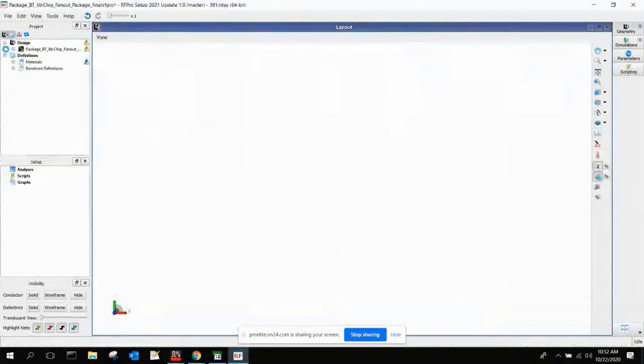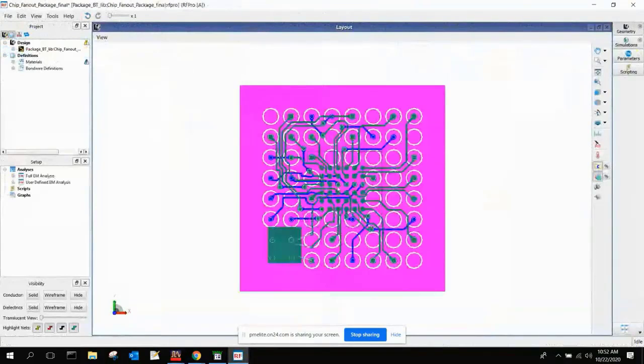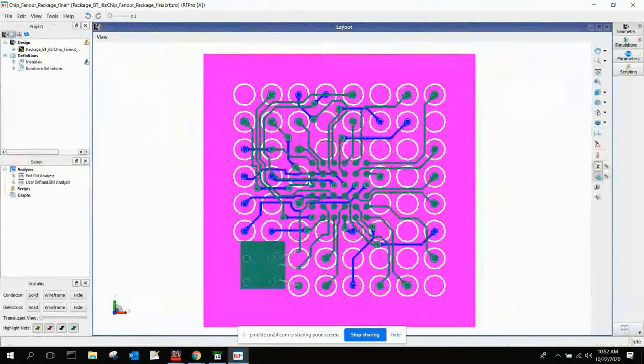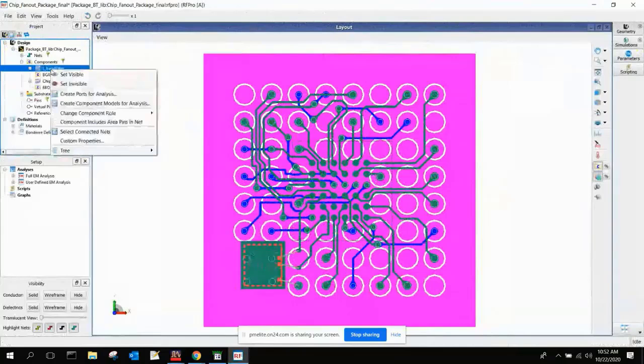So when this comes in, the first thing you might notice about it is that you only see the package layer. So we can do an EM simulation on the package. That's because these components have essentially a role, and these are designed as circuits. So really what it's saying is, okay, I'm going to treat the things that aren't the package technology as circuits. So I can change, in this case, like this is the RDL.